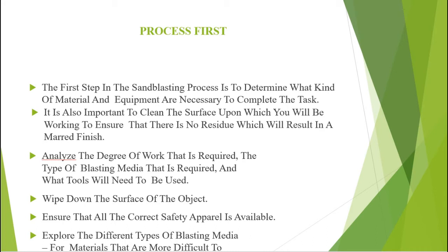Analyze the degree of work that is required, the type of blasting media that is required, and what tool will need to be used. Wipe down the surface of the object. Ensure that all the correct safety appliances are available. Explore the different types of blasting media for materials that are more difficult to work with.